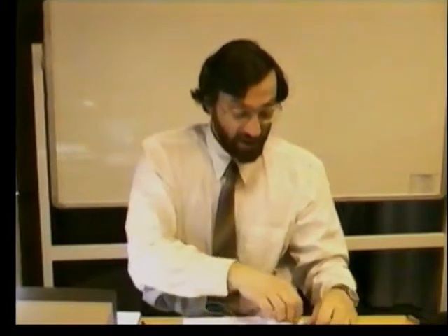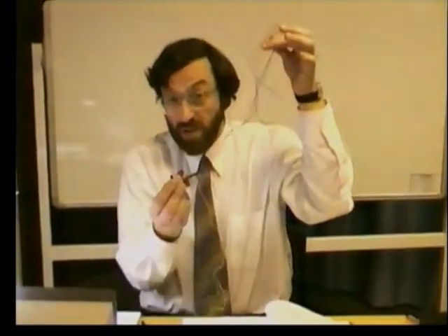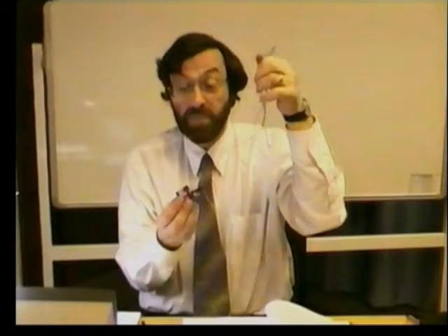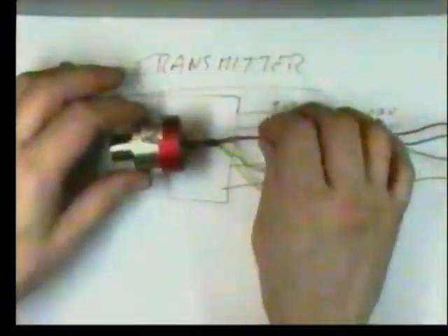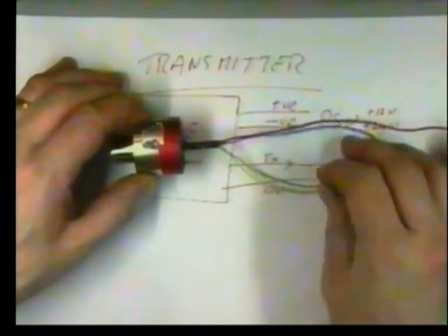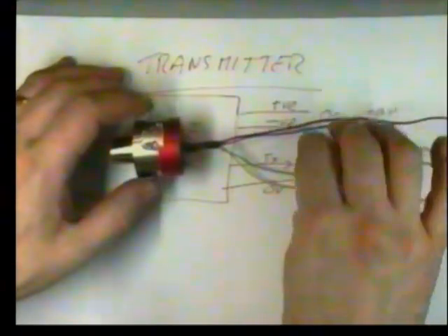If you have a very noisy environment with a lot of electrical interference, the voltages that are modulated down the actual power supply can be quite corrupt. You have to smooth them out to drive your electronics, and so you want to keep these very nasty unsmooth voltages and signals away from the transmission line. So they need to be independent in noisy environments. So let's look at our picture now. We have our transmitter, our power supply, and our signal.